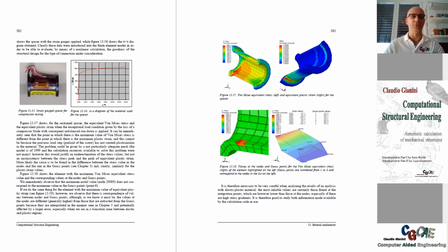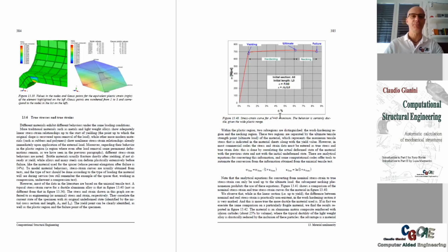Clearly this is done to see what happens for an exceptional load case, like a fan blade out. When one of the blades of the compressor is for some reason lost, there is a rundown which runs clearly unbalanced, and it's generating huge forces on the flange connection. And here we go very deep into details to see what happens to this thing with the nodal stresses and the Gauss stresses that we mentioned in chapter 3.